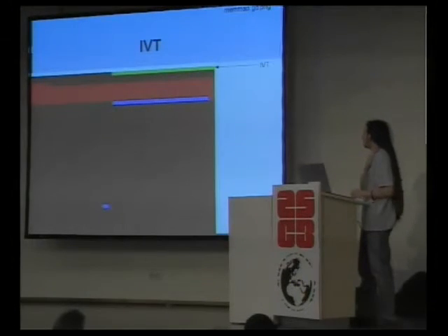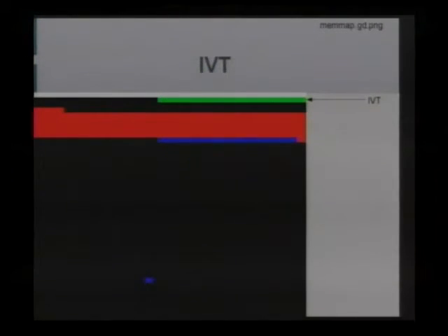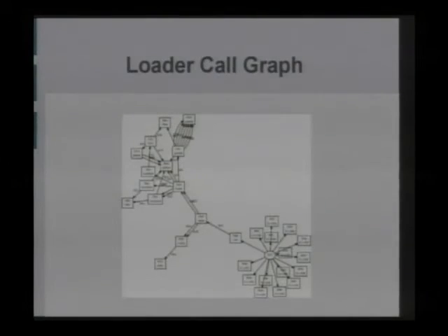And then to zoom in on the interrupts table, you have the green interrupt vector table at the very top. That's 0xFFE0 to 0x10000. And then beneath that, you've got the blue region, which is for proxying interrupts. It's a second interrupt vector table for the lower unit that's not implemented in hardware, but is instead implemented by proxying functions. So at the bottom right here, we have the IVT as a circle, and then all of its handlers come out from it.